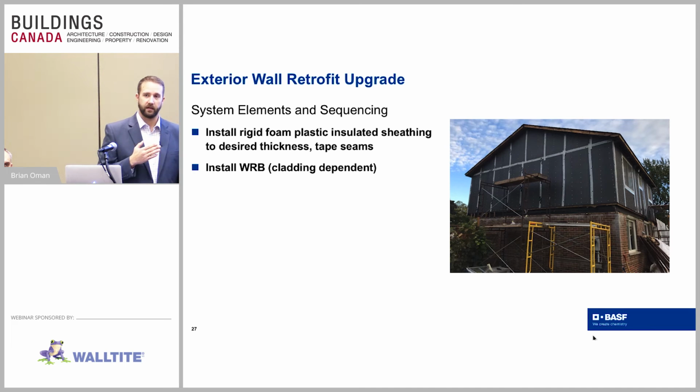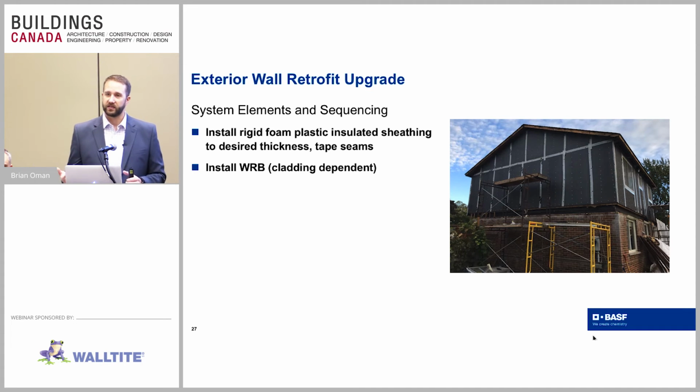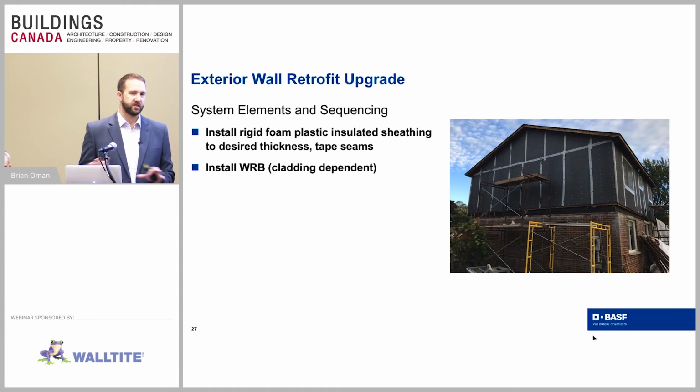So in this case, we're using the expanded polystyrene as our insulating exterior sheathing. So one of the questions may be, what about structural, right? We took off potentially a structural sheathing. What are we going to do in that case? There is testing that is available that shows that the closed cell spray foam that's been applied in the wall cavity can actually provide the structural strength, the racking resistance that's needed for that wall assembly. So we don't actually need the structural sheathing on there to provide the racking strength, the structural strength that the building code requires.